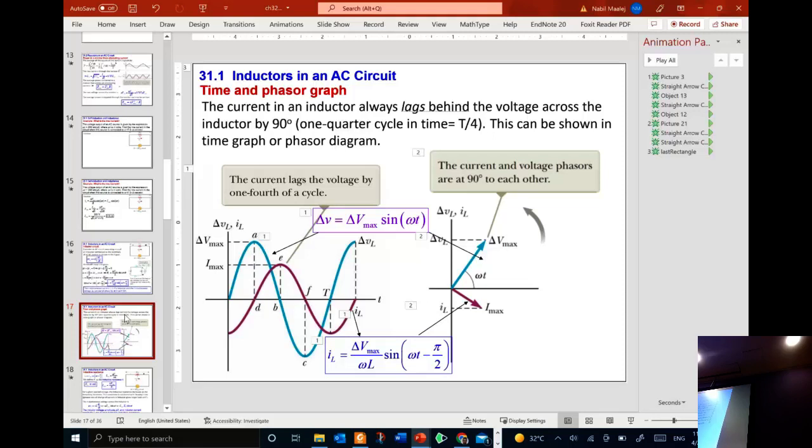Voila. That's why it was there. Okay. So, well, let's use the Serway convention. It's delta V_L equals minus L dI/dt. Okay, and unfortunately, you should have flipped this one. He's using the same figure as other textbooks, but he should have flipped this one because in this case, delta V_L is minus.